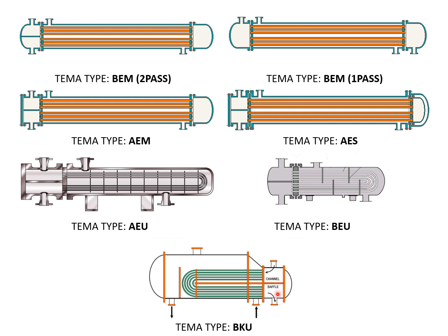This is B, this is B. It is not required that you start from the left. You can start from the right also. You can define your exchanger from the right also. So B, then you have K. K is the reboiler. If you use this kind of shell arrangement, it is called K, that is kettle type. So we take a kettle type reboiler. So K, and then U means the U-tube.